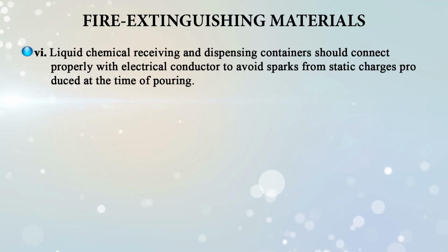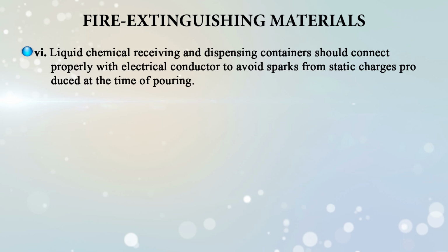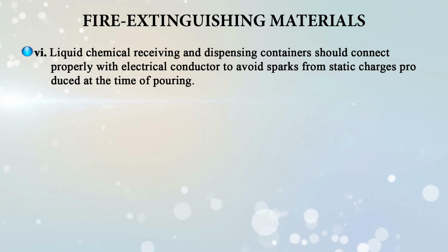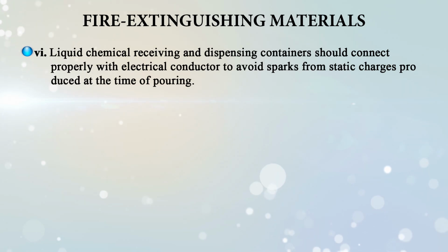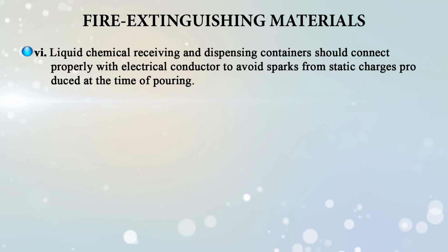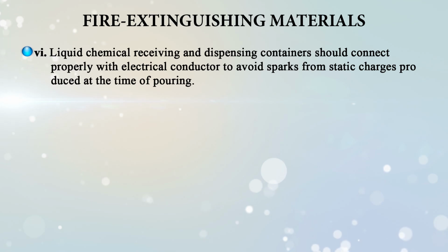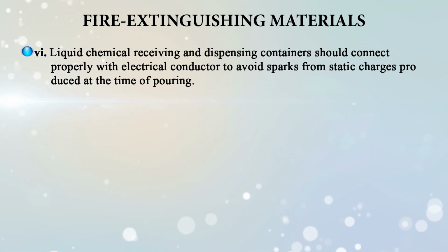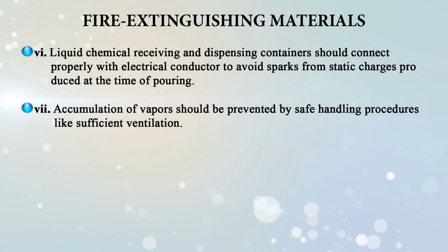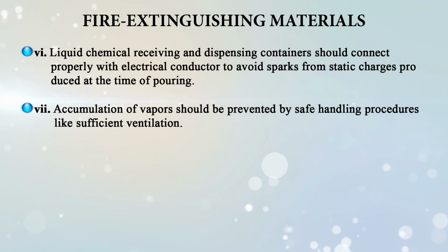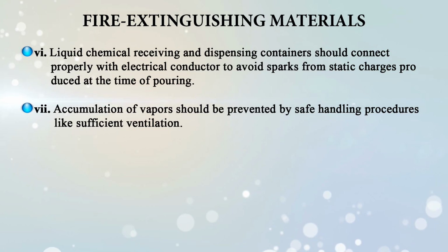Also, liquid chemical receiving and dispensing containers should be connected properly with an electrical conductor to avoid sparks from the static charges that are produced at the time of pouring. Another factor is that accumulation of vapors should be prevented by safe handling procedures like sufficient ventilation.